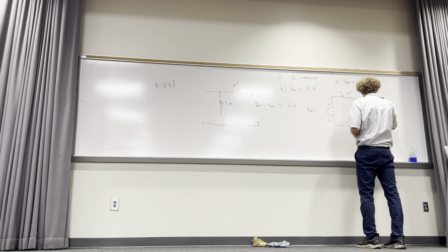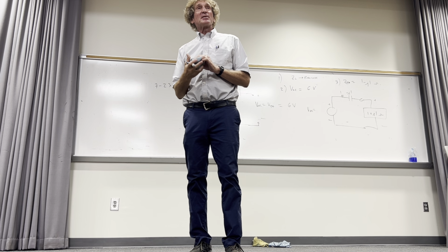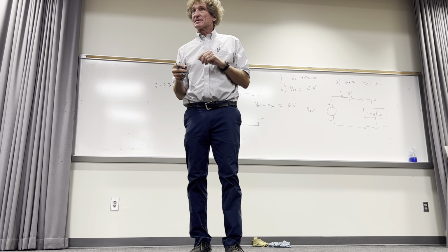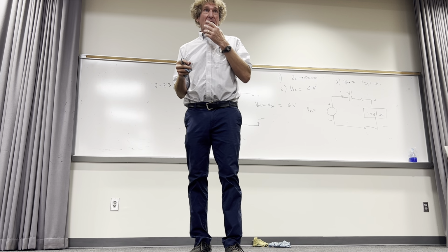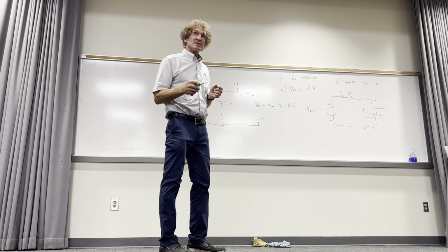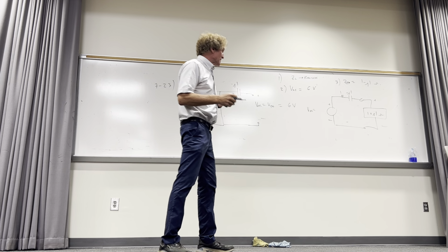All right. So it'd be what? 1 plus J1 ohms. How many see that? It's the conjugate. Correct, class? Now the way you know is the imaginary component will cancel if you add them up in series. It has to. That's just the way it is. Do y'all follow me? And that, in fact, would maximize the amount of power coupled to the load. Got one last question. All right.